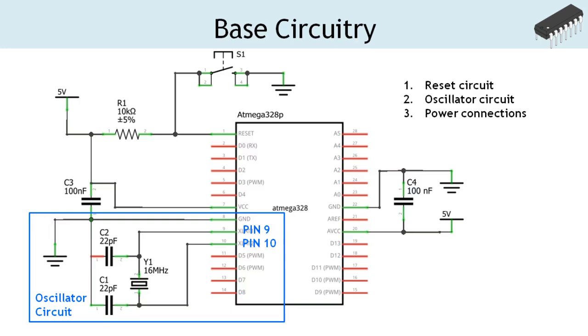The fuse bit of the microcontroller must be configured appropriately to use the external crystal oscillator. We shall see how to program the fuse bits in subsequent lesson.